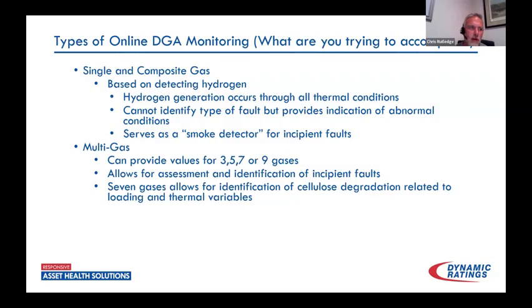And then we also have several fuel cell membrane type monitors out there, where you're going to see a percentage of hydrogen, a percentage of acetylene, percentage of carbon monoxide, and maybe a little bit of ethylene as well. But basically, hydrogen is our key gas that we're looking for, as it is generated with most abnormal conditions that would occur inside a transformer tank.